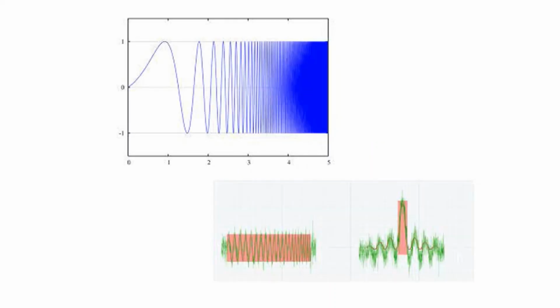So why did I use chirp signals? Well, it's very common either in sonar or any kind of imaging application to use a chirp. And why is that? It's because when you run a chirp through a match filter, you get a very nice spike, which is perfect for imaging and making closely resolved images.